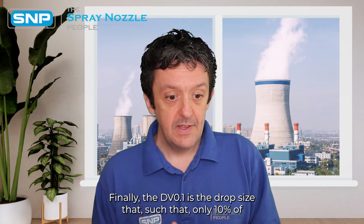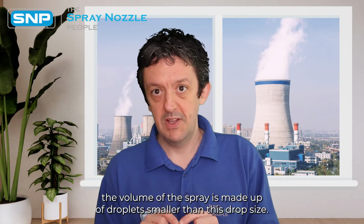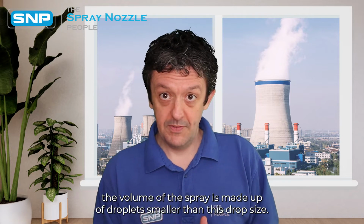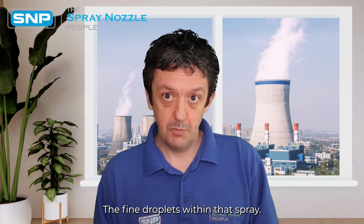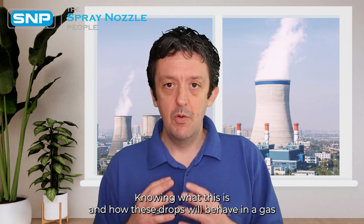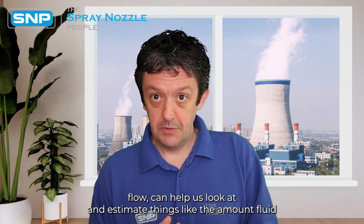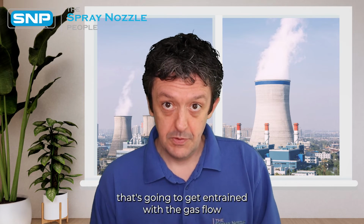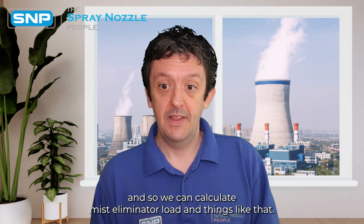Finally, the DV0.1 is the drop size such that only 10% of the volume of the spray is made up of droplets smaller than this drop size. So this is the measure of what we call the fine droplets within that spray. Knowing what this is and how these drops will behave in a gas flow can help us look at and estimate things like the amount of fluid that's going to get entrained with the gas flow, and so we can calculate mist eliminator load and things like that.